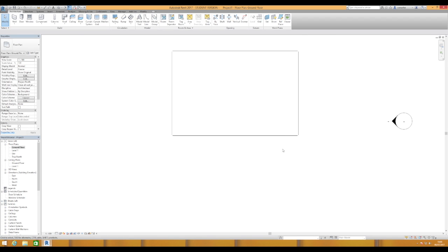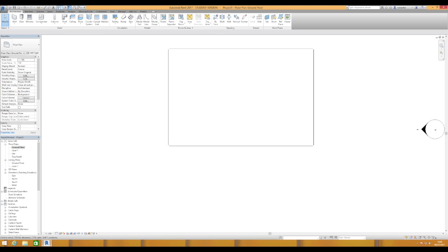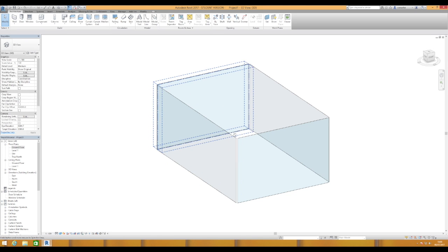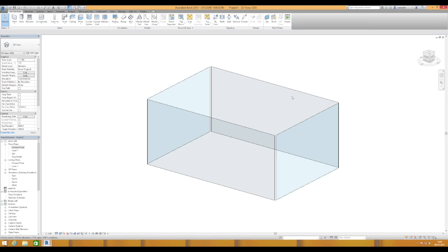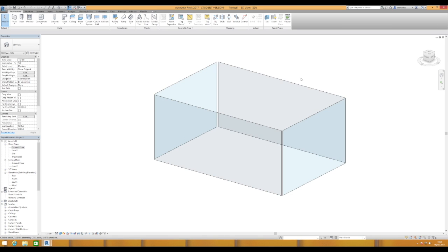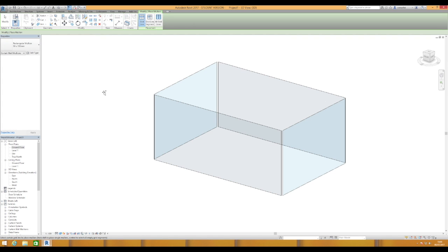Now, the next thing we'll do is, I'll do this from a 3D view because it's a little bit descriptive. I might just put some mullions on first to make it look a little bit better. So if we go into the mullion tool up here, once again, a typical mullion that's used here in Australia would be 45 millimeters by 150 millimeters, and that's the mullion that gives you that full 52 millimeter glazing offset.